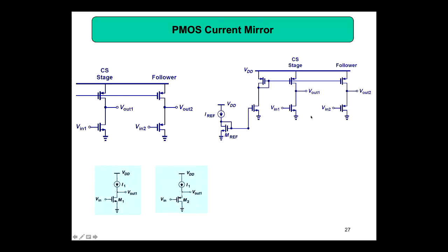Then what we need is what we did before for BJT. You got a PNP current mirror, then we use an NPN current mirror for biasing the PNP. Same with the MOS. In the MOS, this is a current source, so you are getting a PMOS, and for this one also you are getting a PMOS. Then we connect them together because we want to make only one current mirror for biasing both. Then you connect together. So this is the one.